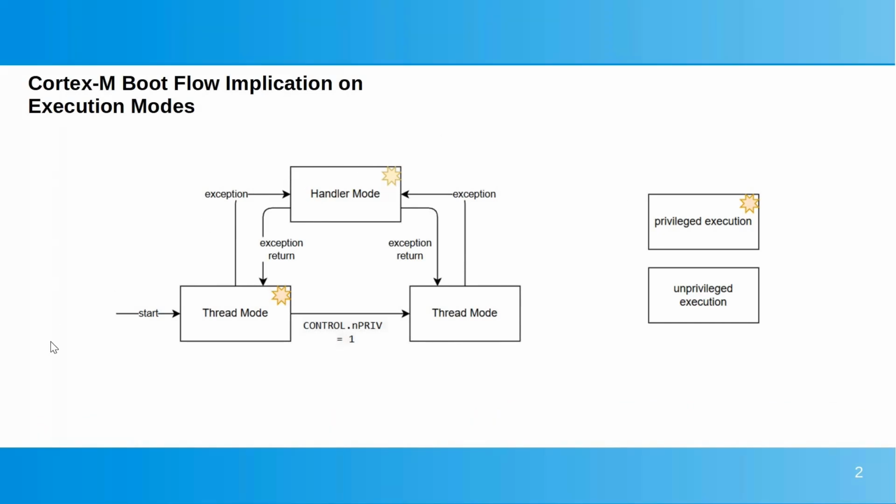After boot up, or to be more precise, after the power on reset sequence, the ARM Cortex-M microprocessor will boot in thread mode. So your reset handler, which is the first function to be executed by your program after reset, will execute in thread mode.